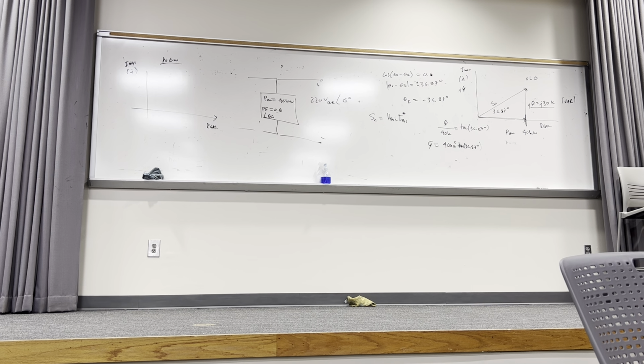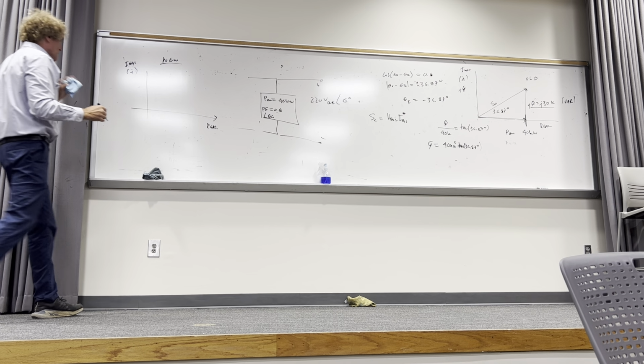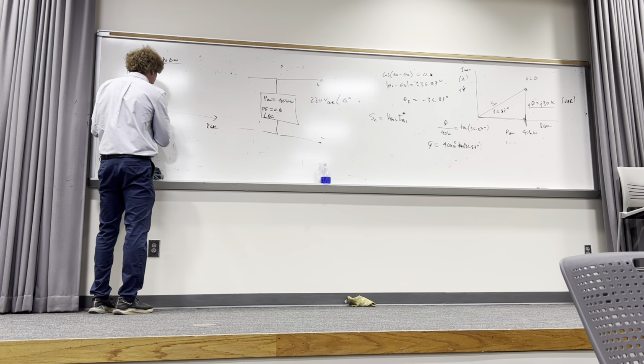You had a capacitor, it can't change the average power dissipated. The real power is the same. Out to here is 40 kW, and that's actually PAV here. That stays the same, but something does change.